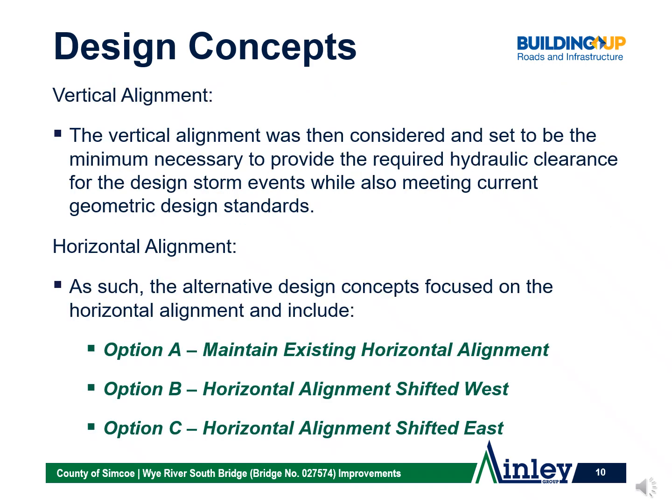The vertical alignment was set based on the minimum height necessary to achieve the required clearance above the design water level at each structure location, and this was carried consistently through all of the design concepts.